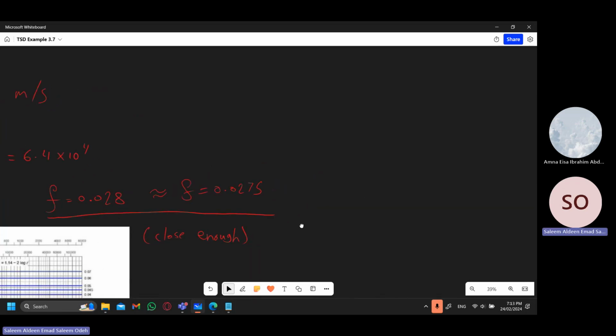So now since we have a proper friction factor, and now we have a proper Reynolds number, we have a proper velocity value, and no, we don't. We need to recalculate both our velocity values and our Reynolds number because now we have a new friction factor.